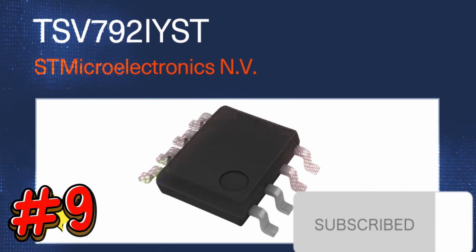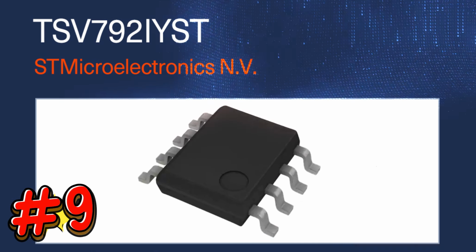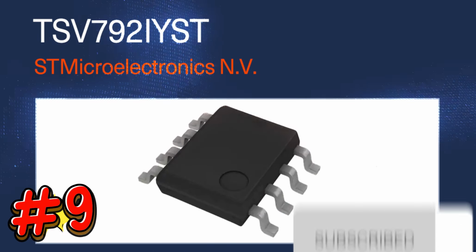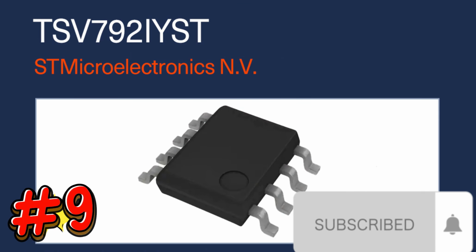The rail-to-rail input stage and the slew rate of 30 volts per microsecond make it ideal for low side current measurement. The benefits of the TSV92I-YST are that the measurement accuracy is virtually unaffected by noise or input bias current, and its signal conditioning is excellent for high frequencies.